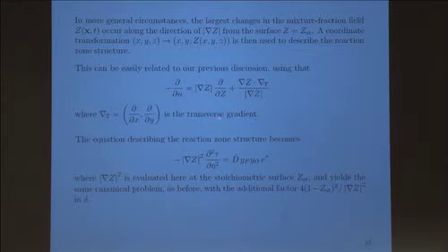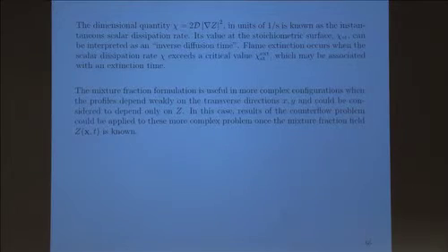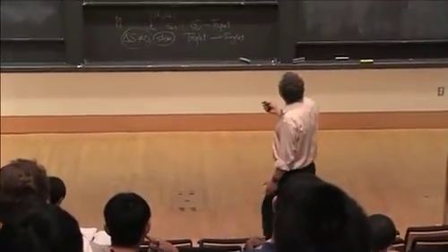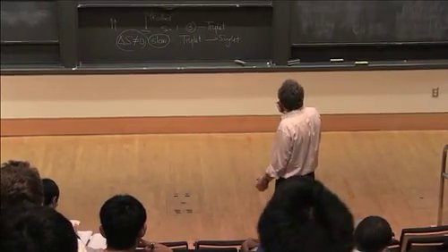In fact, if you do it in the normal coordinate, what you will see is that when you derive your equation for the reaction zone, in front of the diffusion term you're going to have this gradient of Z squared. And that term, in dimensional form, has units of 1/s, and it's known as the scalar dissipation rate. It's a quantity denoted by chi, and it's related to an inverse diffusion time. So that's effectively like changing your Damköhler number.